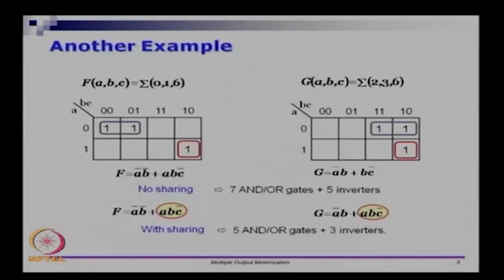And when you do that, for example you see that this term can be shared here and here. If I had not been careful I would have grouped this, however if I see that it is being shared, maybe just allowing for sharing is better than cutting down the hardware only for G, but you will still have that number of gates for A. So it is better to make only one copy of this term here and leave it as it is.